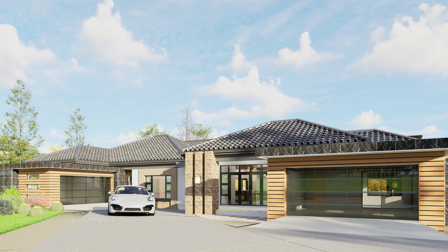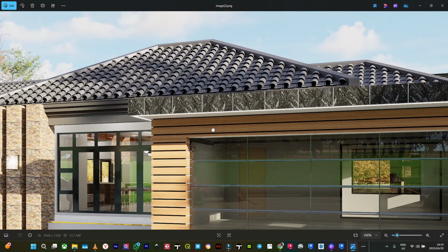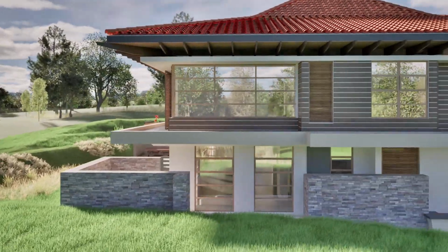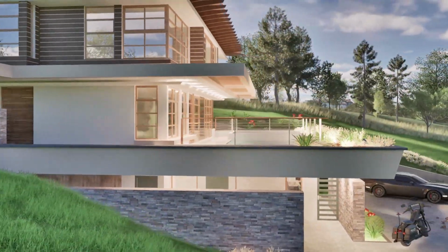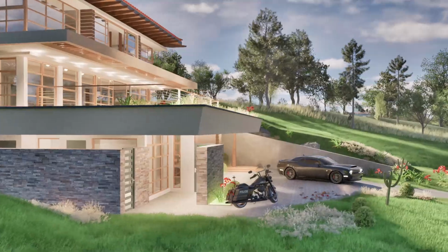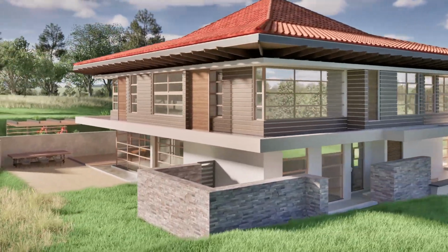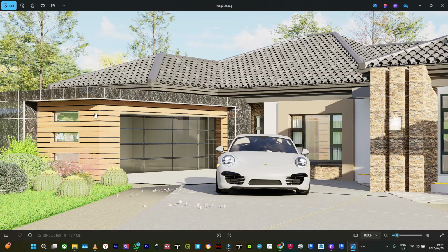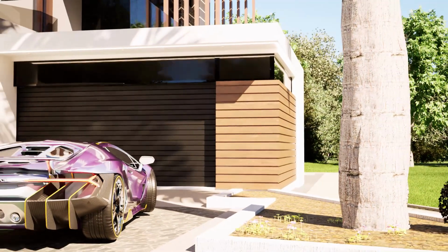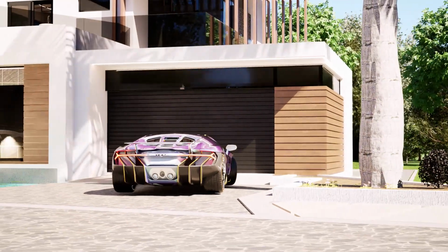Yeah, so this is where I used that cladding tool to do this cladding here. The nice thing is that it moves along with the wall. It's like in Revit, when you have your toilet or other components that are hosted onto the wall, wherever the wall goes, so will the cladding. And the cladding can be put on its own layer, whereby you can hide it in plan. Perhaps you don't want to see it in plan, but you want to see it in elevation. So yeah.